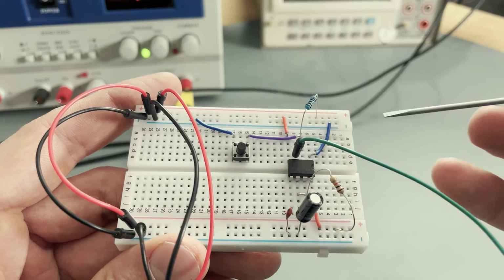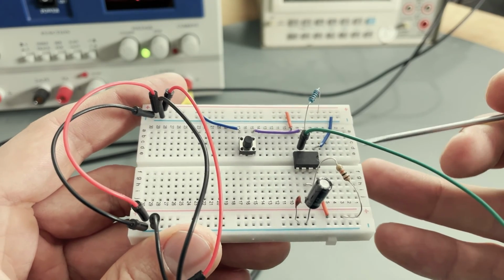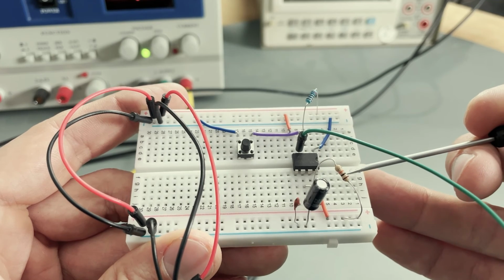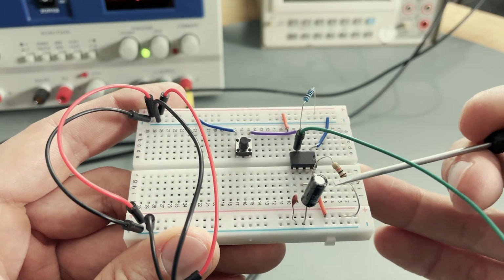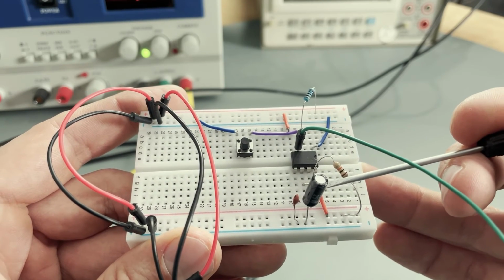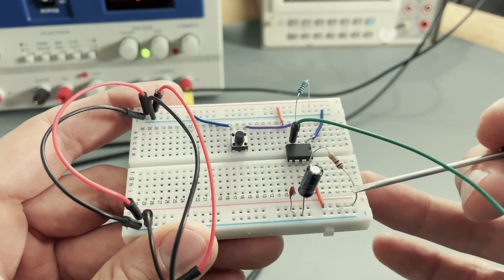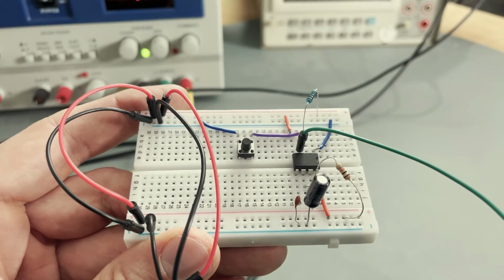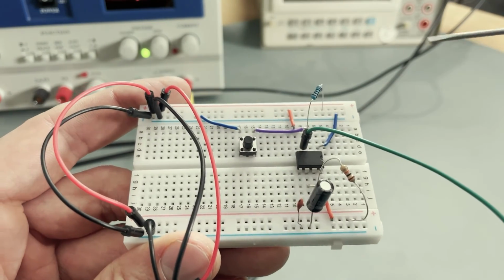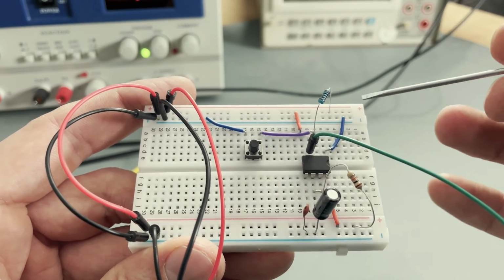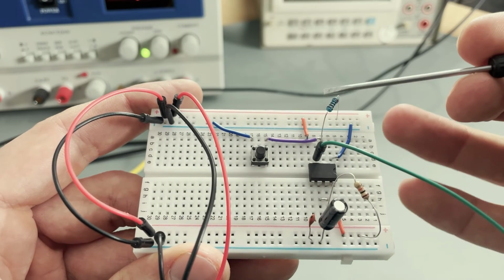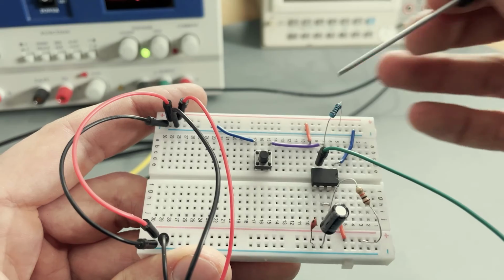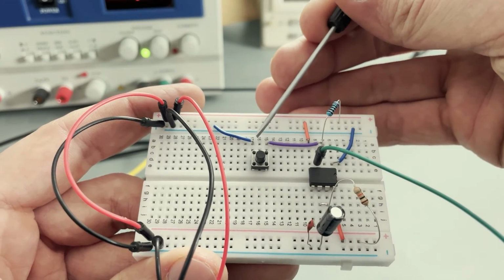So this is the physical setup that we're working with. Basically, we have our RC right here. This is the 10 kilo ohm resistor that I mentioned earlier, and the 100 microfarad capacitor right here. This smaller ceramic capacitor on the other side is simply the one on the control input so that we don't have the noise. And then over on this side, we have just a simple resistor that protects us from shorting VCC to ground, and I have my tactile switch right here.